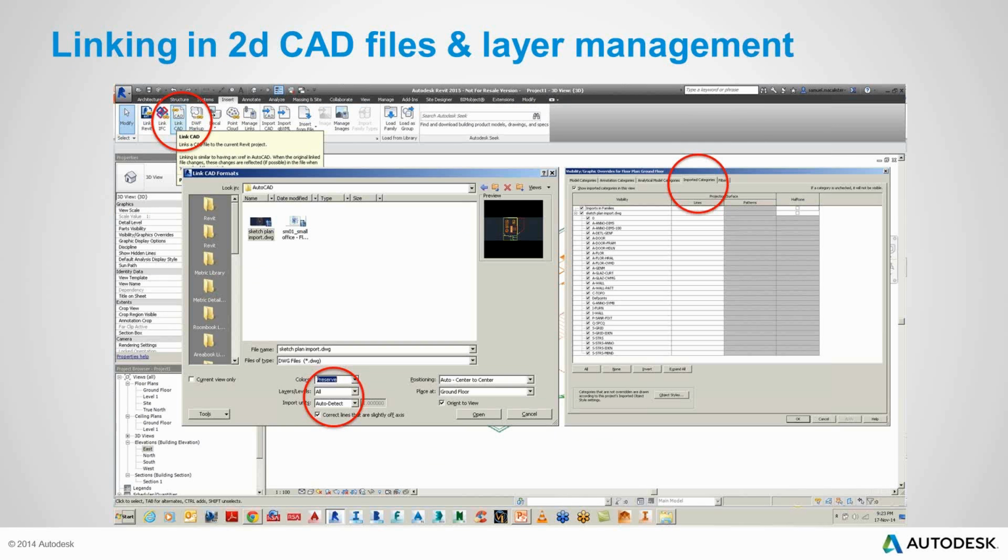When you're working with CAD data, whether it's SketchUp data, DWG, DGN, you can link this data in or you can embed it. Sometimes it's better just to link it in, because sometimes if you bring the CAD files in and embed it in the file, it can remain there for a bit too long. So good practice is to link a CAD model in.